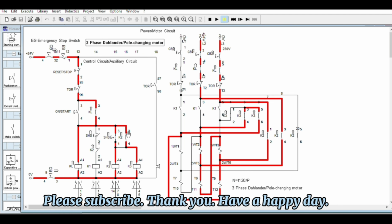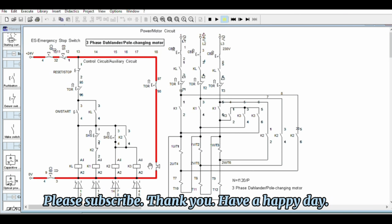Okay, this is the latching contact, by the way, not interlock, but these are interlock. You have the option to use this one if you are using the normally open push button. If this one is used, then you may omit this one. Emulate overload relay. Okay, you may add some signals there, lamps, or even this one. You can add simulation lamps there, pilot lamps. Do not just reset the overload relay, but find what causes the tripping, the overload or the overcurrents. Turn off circuit breakers.